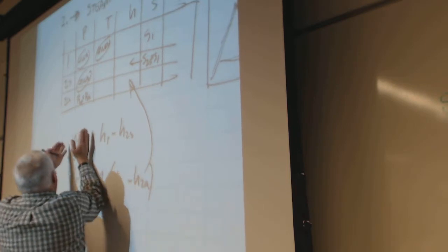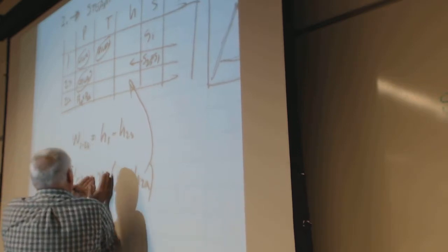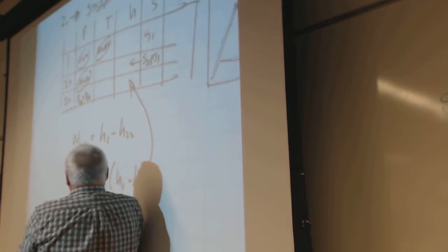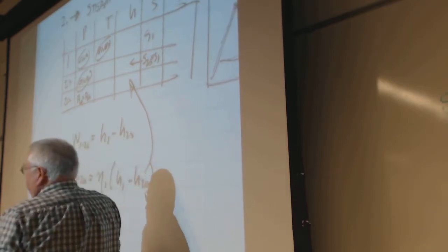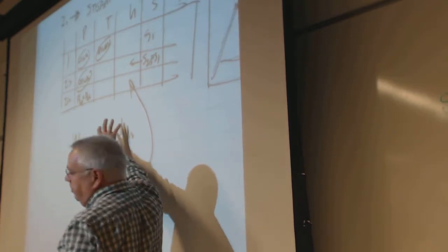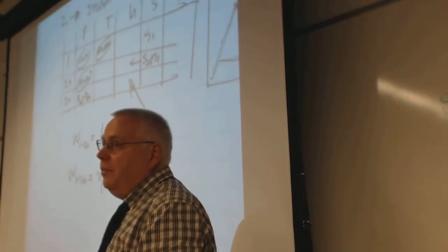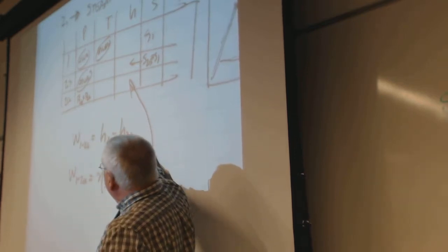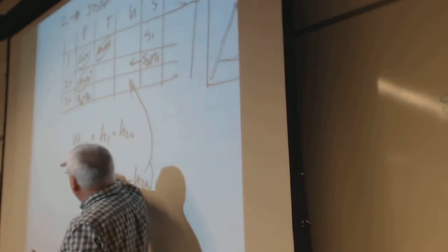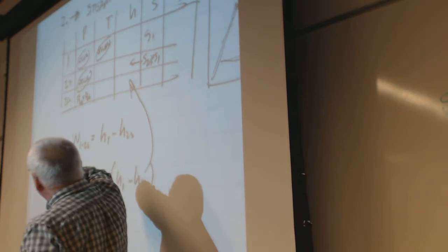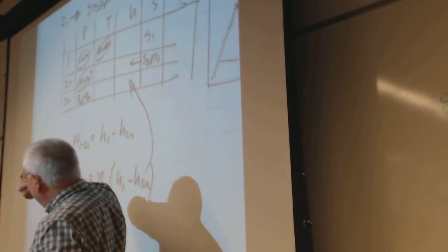This is the amount of energy that's available to be converted, and this is how much actually got turned into work. That's what the isentropic efficiency comes about. This isentropic value just tells us, if we had an isentropic turbine, all this would be turned into work, but it doesn't happen. That's what it will limit. So I'll be looking for this number and that number and filling all this stuff out. So you'll be looking for the difference in enthalpy.